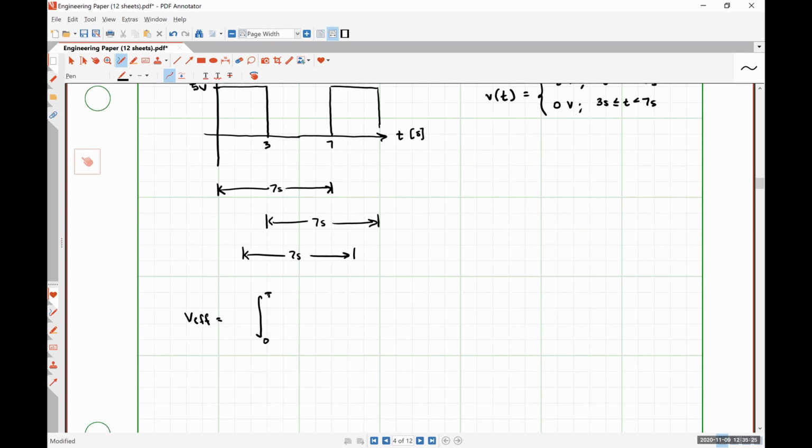The voltage squared, okay? So we're not going to be looking at V of t. It's very important that we remember to square the voltage waveform. All right. So this is giving me the area under the curve, or the area under the square of the waveform. The effective value is in some ways representative slightly of the average. So we're also going to have to divide by the period, right? If we have a signal and we want to know its average value over one period, we integrate over one period and then divide by the length of the period to get its average value.